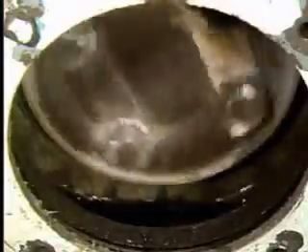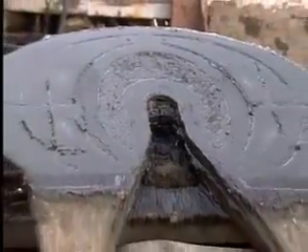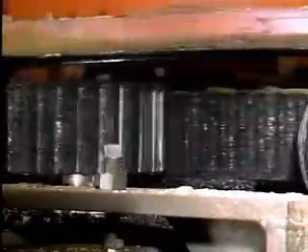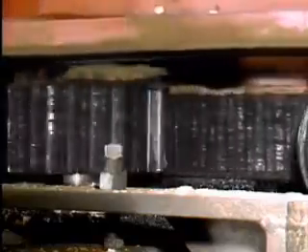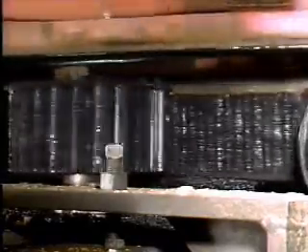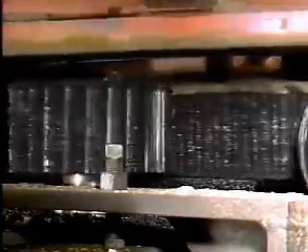Oil's ability to flow freely can make it unsuitable as a lubricant in some situations. In situations where a lubricant must stay put, a different type of lubricant, such as grease, is needed. Grease is usually the best choice in situations where a lubricant must stay in place. For example, grease's ability to stay in place makes it the best lubricant for exposed gears. There's no gearbox to hold a supply of lubricant, so the lubricant used must be able to stick to the teeth.